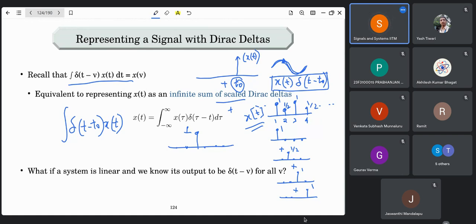When this addition is going to be in a continuous domain, it becomes an integral. So basically all that we have written here is just addition. Because it is continuous, this t naught is taking infinitesimally small values, so we are going to say that this is an integral, not an addition. And because you're integrating, you're going to add a dt naught. And this t naught is from minus infinity to infinity. Basically, it's just taking each and every sample that is present inside this continuous signal and adding them together. That's the representation that we have here.